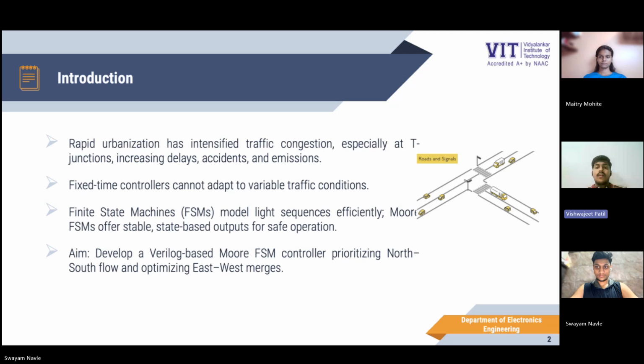Specifically, we use a Moore FSM architecture where the outputs depend only on the current state, ensuring predictable, stable, and hazard-free transitions, an important feature for safety-critical systems like traffic management. By implementing this on an FPGA platform, we achieve fast, deterministic control, low resource utilization, and high scalability for smart traffic